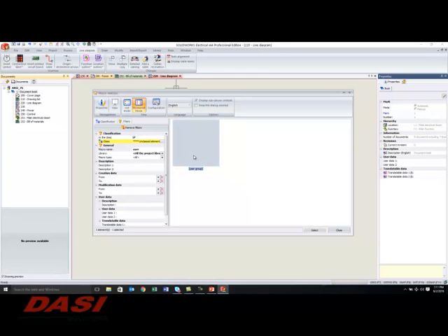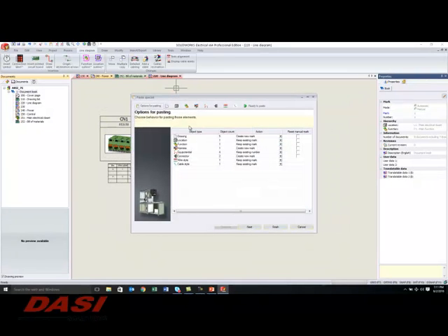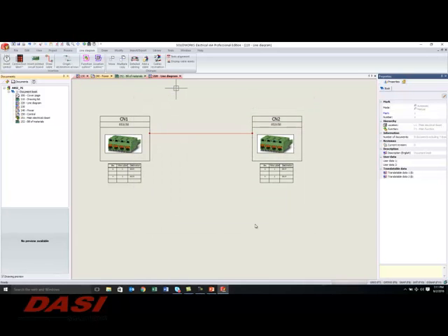Of course, it's not going to give me a preview because there's so many sheets, but I can now highlight that, drop that in. It takes a second. It's going to automatically ask me, okay, I've got that existing project. It's got all these numbers and all these connections. What do I want to do with it? Do I want to keep existing information? Do I want to change it to new stuff? So I'm going to keep most of the stuff, but I'm going to change those connectors. I'm going to tell it it's got a new tag, new identifier. I simply come over here and say finish. And now it will take a second, but notice that it creates that entire set of drawings over again.